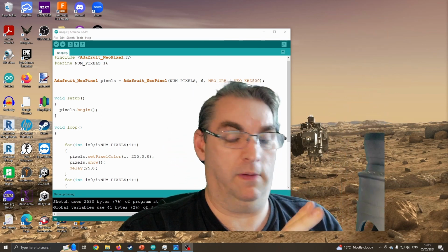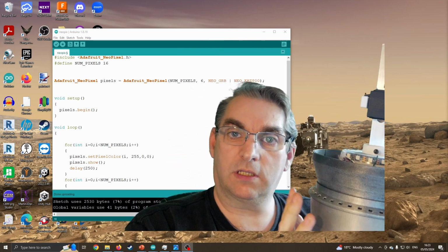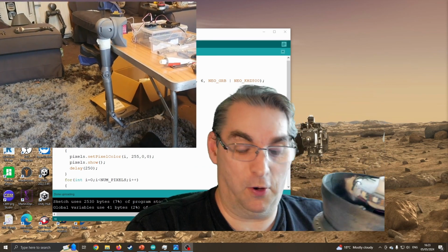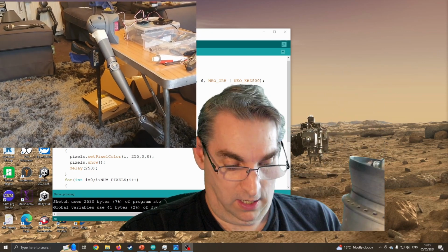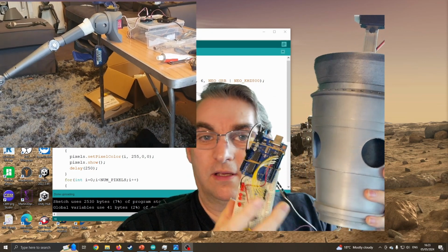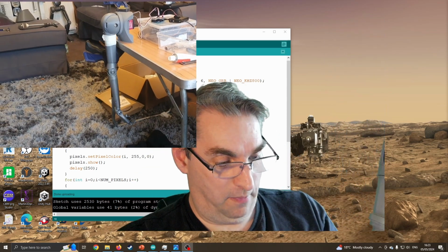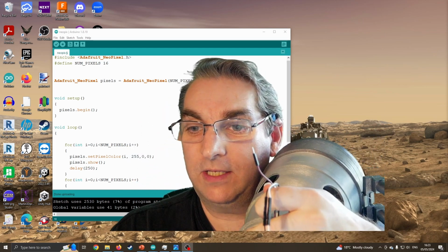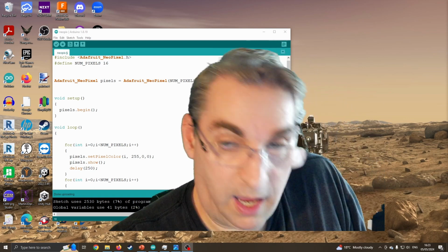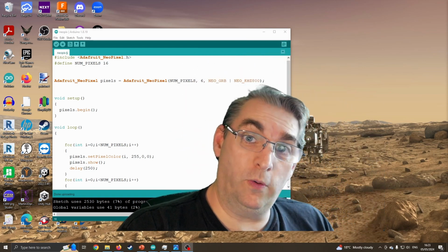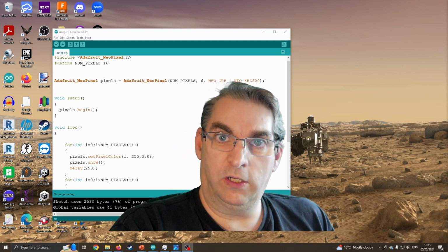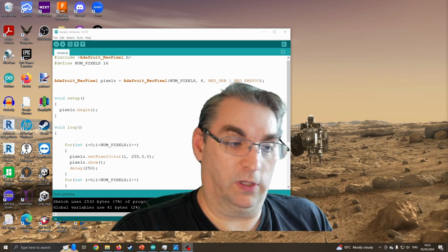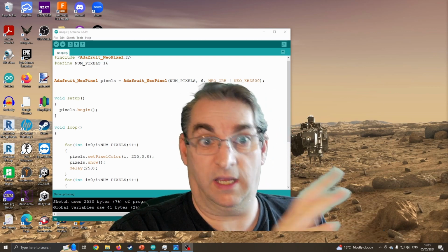Unfortunately at the moment, this was fully working, but IG has kindly donated a lot of his parts over to Flow, so I can work on Flow's servo controlled systems, but he will get his own back shortly. So I'm going to use the board we've already created, and connect my data wire, which you can't quite see because I just don't have enough hands. I'm going to connect the data wire into pin 6. I'm connecting the voltage directly to the Arduino Uno, which I don't actually recommend. Normally I'll use a separate battery for the positive and negative, and then give it a common ground. So I'll connect the negatives together, which I'll cover in the second video on this sort of content.